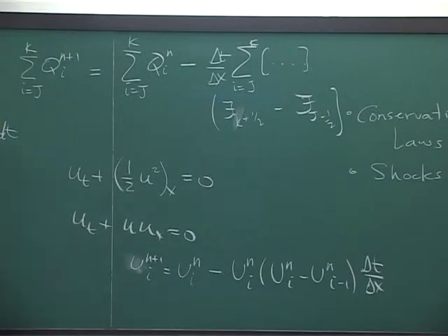We'll see that non-conservative discretizations give you the wrong solutions for shocks. So that's the idea behind doing a finite volume discretization rather than a finite difference discretization.